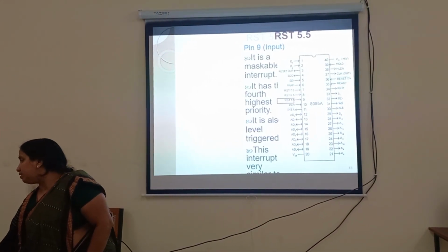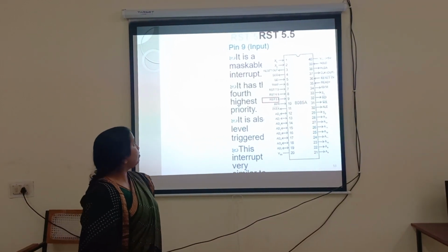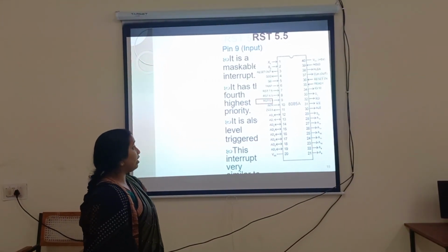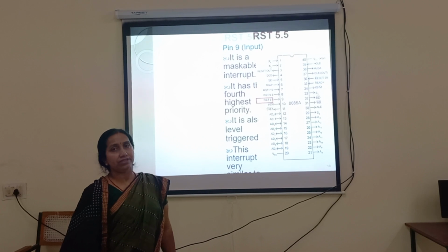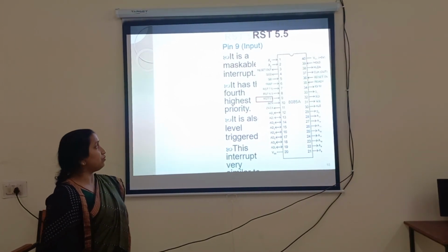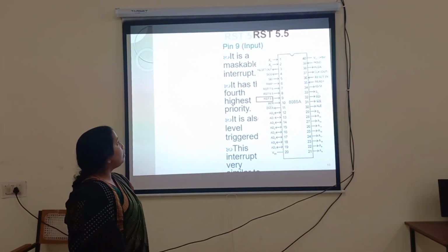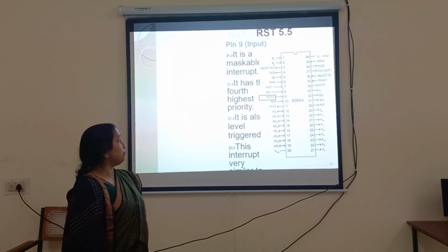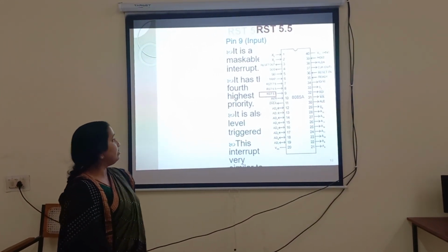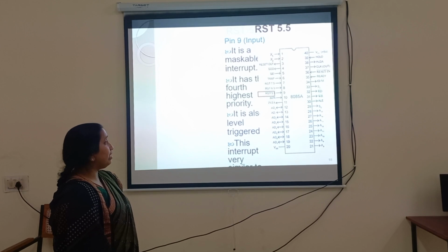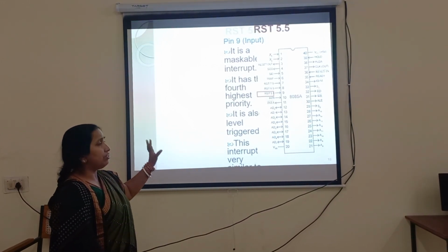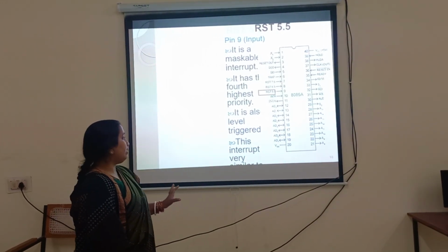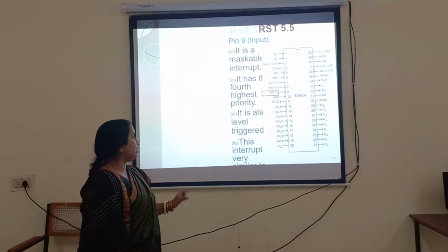The next is pin number 9, which is RST 5.5. RST also stands for restart or reset. 5.5 is also assigned a memory location, and it is also a maskable interrupt, with the fourth highest priority, and it is also level triggered. All the interrupts here are level triggered.